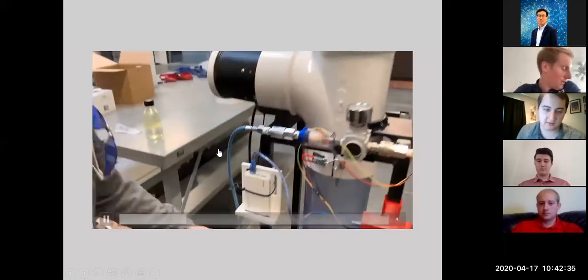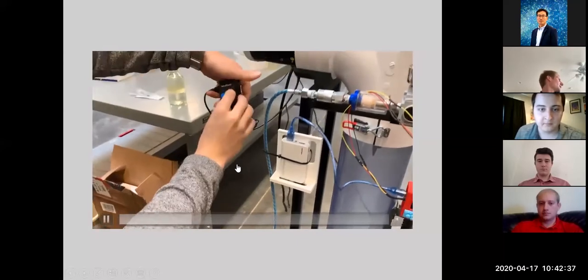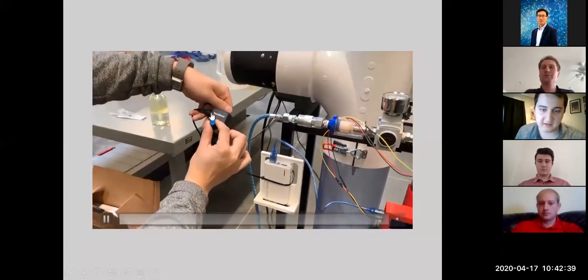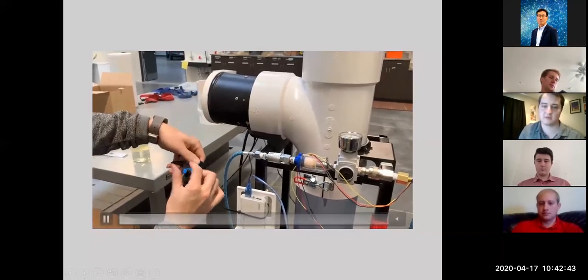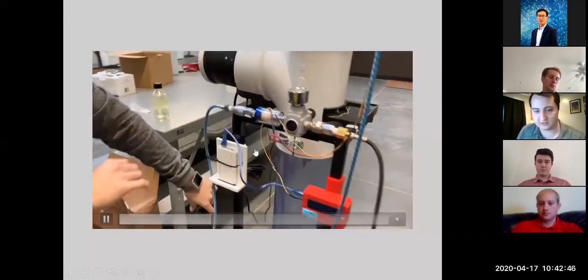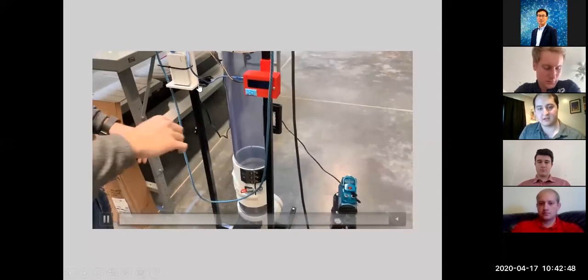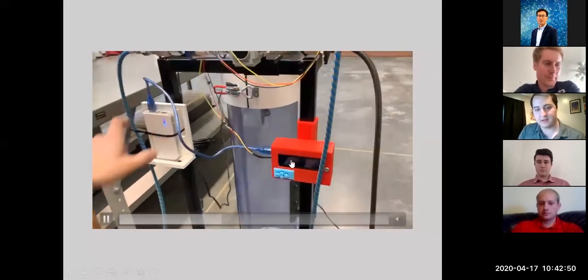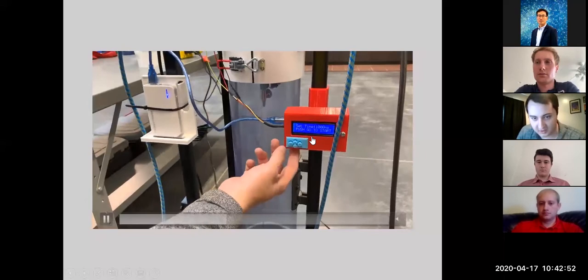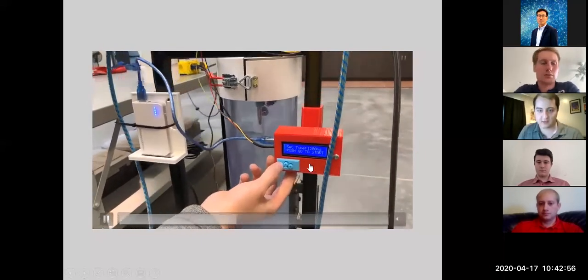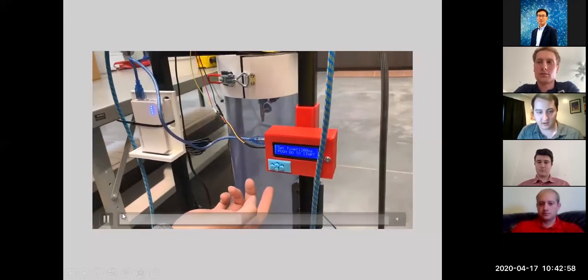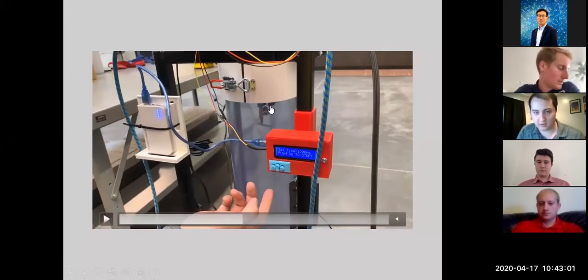Then you turn on the fan setting to whatever you want. You can see it's an adjustable fan, so you have many different options. That's why it's between 4 and 16 miles per hour with the adjustable fan setting. Then you turn on the battery and adjust the Arduino timer to whatever that is. It's in increments of 100 milliseconds, and that's how long it will spray. You can see right here how long it will spray the pesticide into the tunnel.